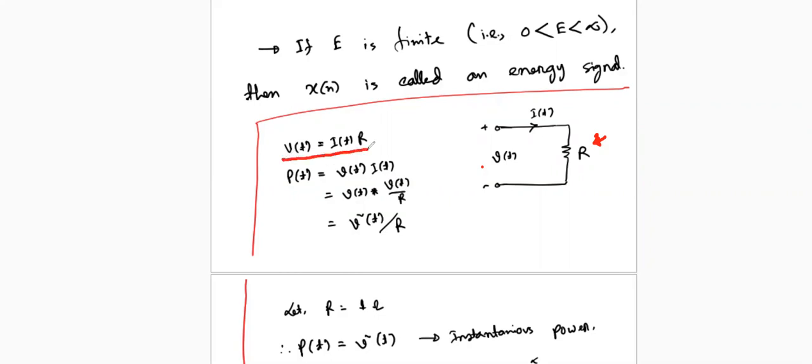This is V equals IR, and we also know that the instantaneous power is equal to VI. We have this because there is no inductive part, so there is no phase lagging or leading, so there is no point in putting the cos theta. So the power P is equal to VI. This is our conventional idea. From Ohm's law we can write that I can be replaced as V by R.